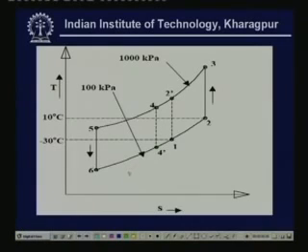This process 6 to 4 is the actual heat extraction process, during which you get the useful refrigeration. Okay. And this is again an isobaric process. This process is taking place at 100 kilopascal pressure, and during this process, because of the heat transfer to the air, temperature increases from 6 to 1. Okay. So, this is the process, and finally process 1 to 2.